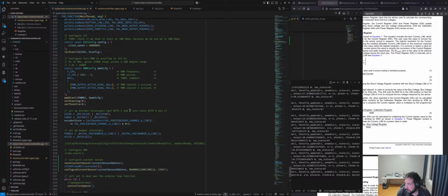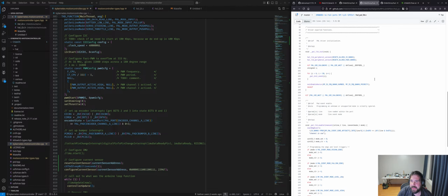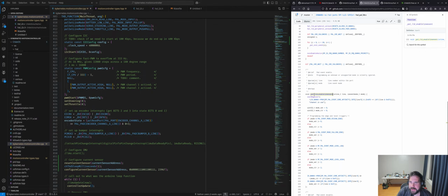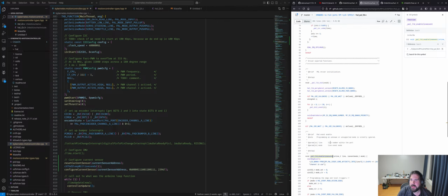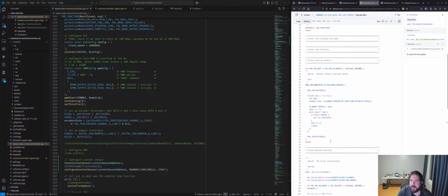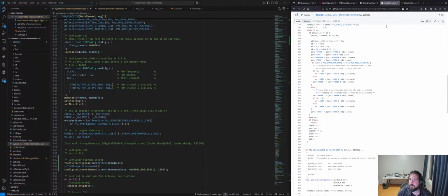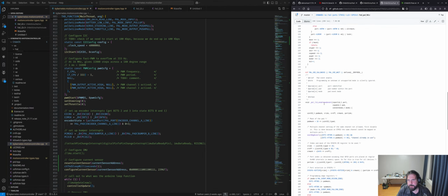I think it would be fun to distill out of this actually implementing those GPIO interrupts for ChibiOS, because I was looking around, and say this is the Raspberry Pi Pico backend for ChibiOS. We can see there's this PAL low level driver enable line event, disable line event, force line event logic. That is how these pad interrupts work, and also in the STM32 driver, we can see enable pad event.